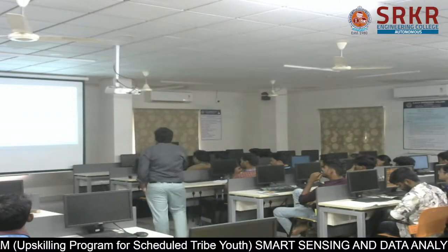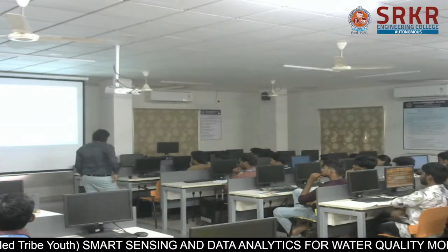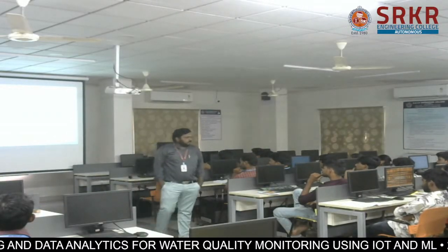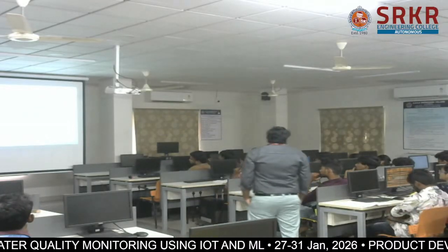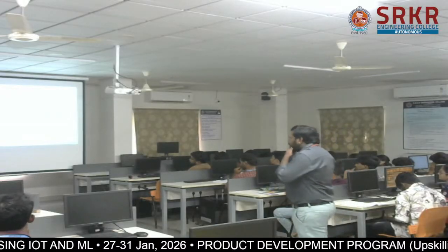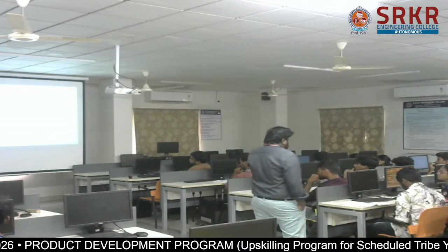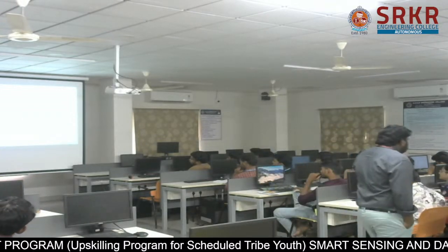If you see sample 1, where pH is 7.2, which is in between 6.5 to 8.5, TDS is less than 500 mg per liter and turbidity also less than 5. Am I correct or not? So everything is okay, therefore the sample is good. If you see sample 3, the TDS value exceeds 500, and if you see sample 5, it is very poor.